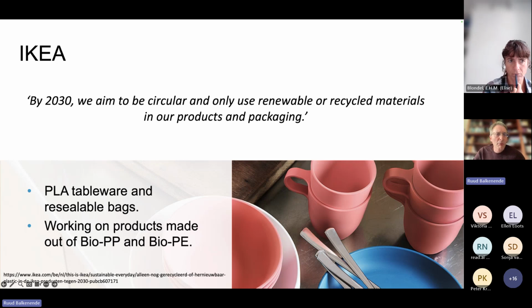This is an interesting example of IKEA, who put PLA cups on the market. Great idea, but don't put hot drinks in them, as the glass transition temperature of PLA is rather low and the cup deforms. But we do need this kind of failure and continue experimenting if we want to get on a learning curve where we can replace fossil-based plastics by bio-based ones.